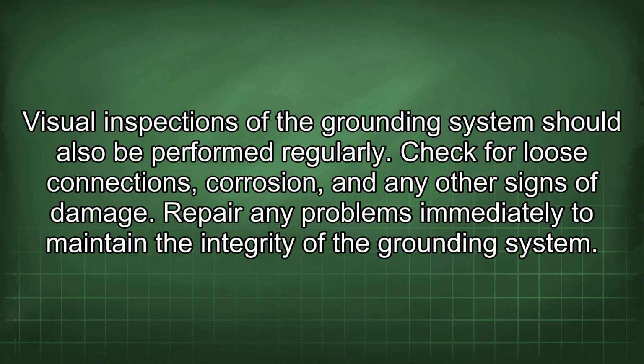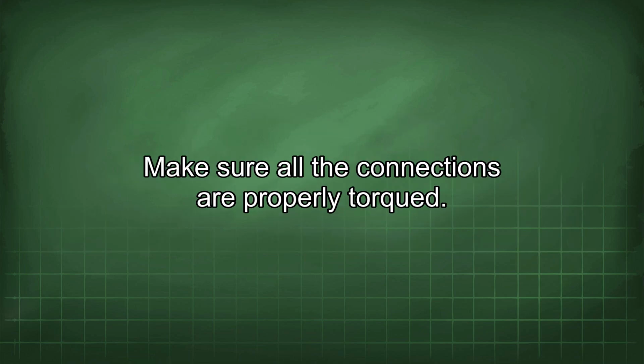Check for loose connections, corrosion, and any other signs of damage. Repair any problems immediately to maintain the integrity of the grounding system. Make sure all the connections are properly torqued.